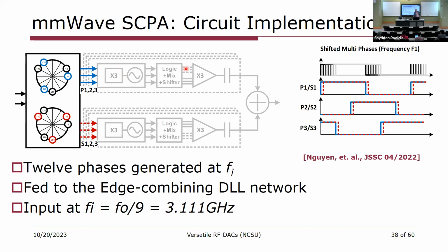Now, at first we decided, well, we're going to try and just triple the frequency at the output stage. But we discovered that distributing 9 gigahertz multi-phase signals across a fairly big chip periphery consumes a lot of power. In fact, it consumed almost as much power as we were saving. So there was really no advantage. And so what we decided to do was to generate all the frequency that we needed locally in slice from a single common 3 gigahertz multi-phase reference that we distribute just to the input of each of these slices.